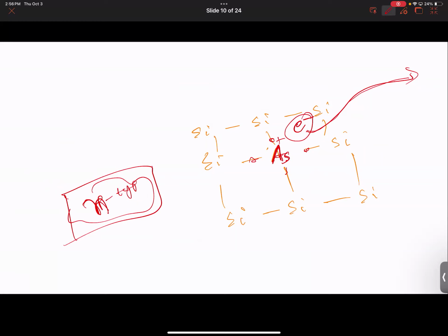But what happens in a p-n junction? That electron that you gave up can move away from the n-type all the way to the other side. It's gone now. So that n side all of a sudden starts saying, hey, where did my electron go? I no longer have that electron that could screen my charge. So now I am a positive charge. Does that make sense? So the dopants that led to extra electrons and extra holes are essentially charged.